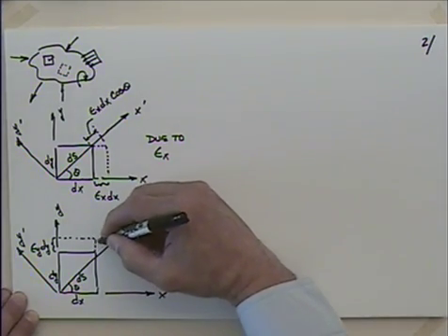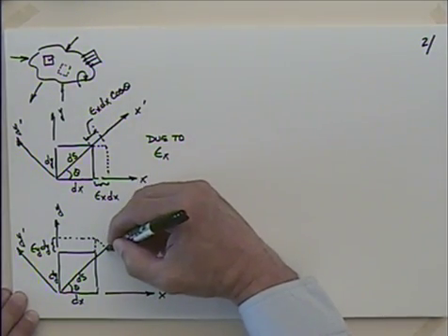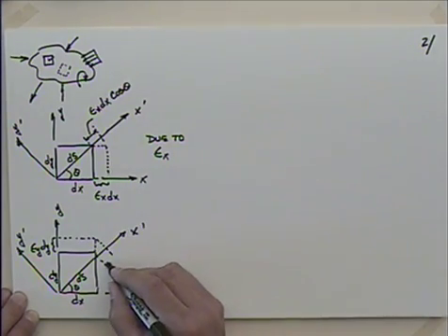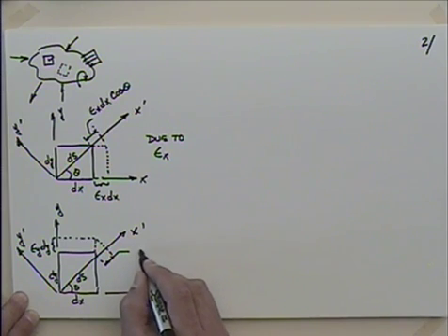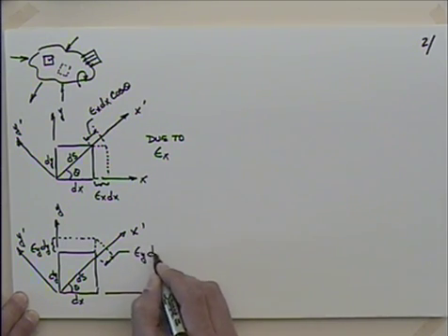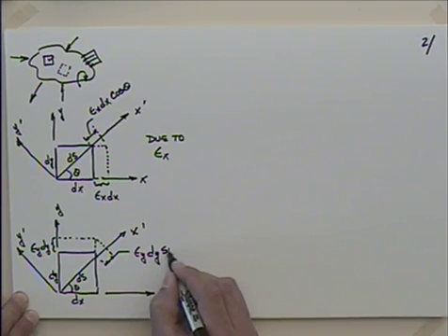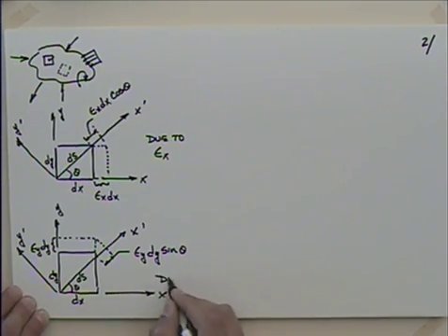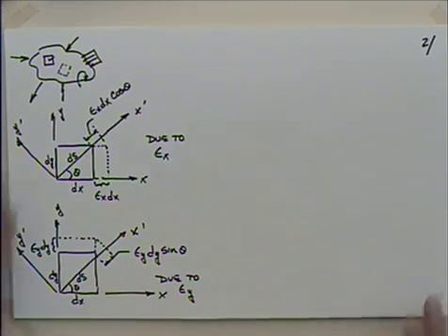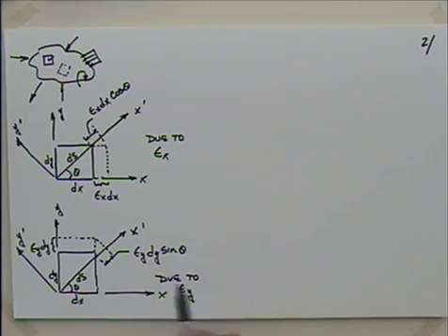So if I transpose that onto this direction, I have something that would be given as epsilon y dy now times what? The sine of theta? You've got the sine of theta there. And this is, of course, due to epsilon y. Now, the last thing that could cause change in the x prime direction would be gamma xy.